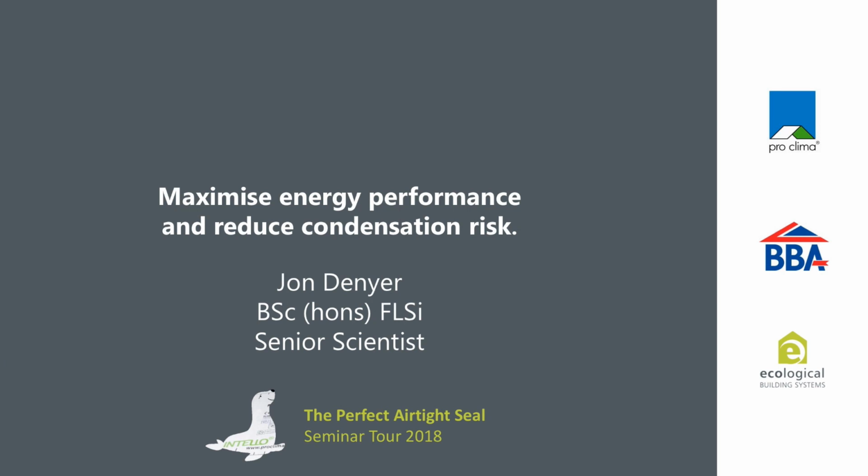For this short session, what I want to do is look behind two of the very important standards: U-value calculations and condensation risk calculations. Because we rely on these a lot, we're all familiar with the BRE U-value calculator, JPA, BuildDesk. It gives nice slick outputs. The U-value is this, condensation risk is this, there might be some graphs in there, and it all looks fine.